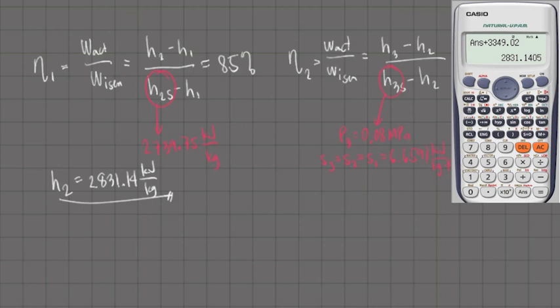Under these conditions, stream 3 is a saturated mixture. It has a quality of 87.5%, and I have determined its value to be equal to 2381.13 kilojoules per kilogram. Rearranging our equation for efficiency, we can now solve for the value of H3, or the actual enthalpy.